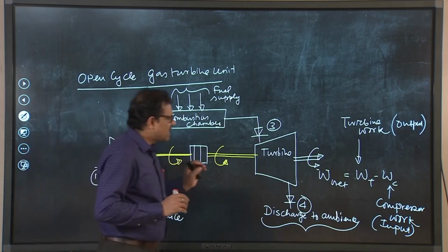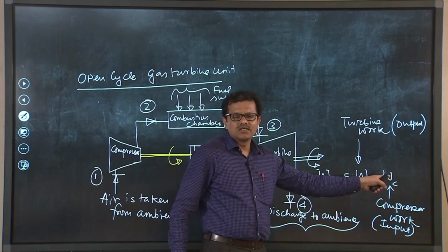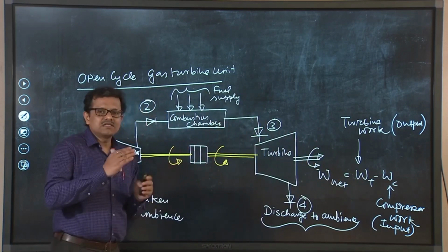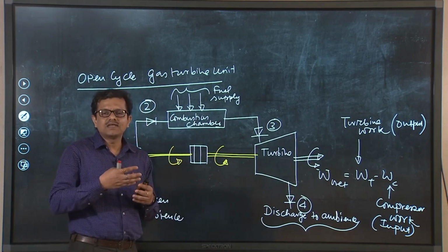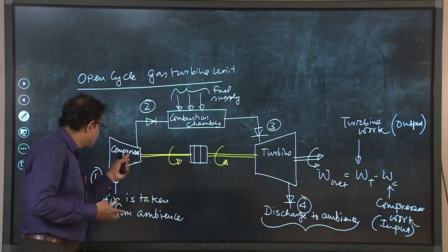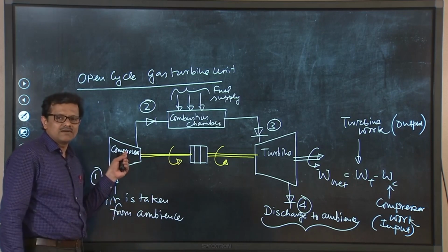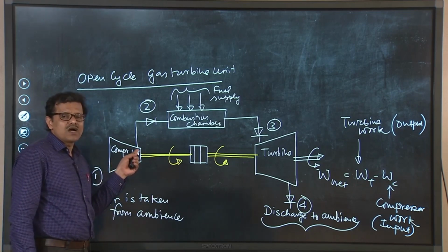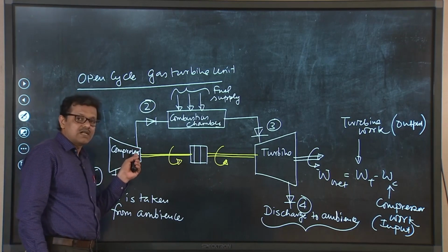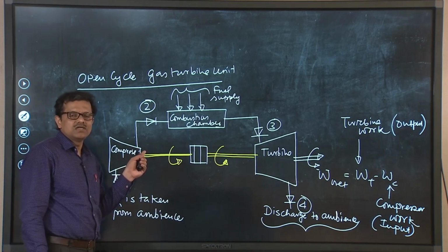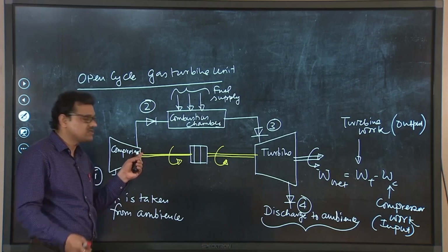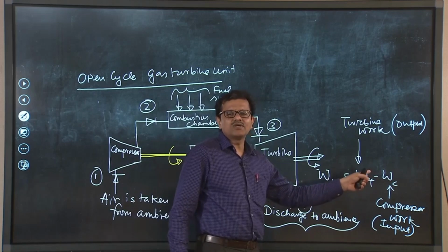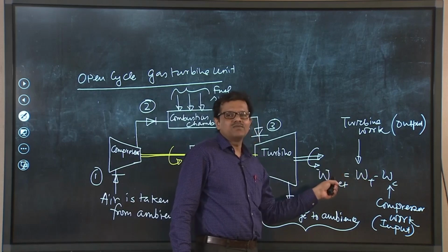Similarly, here I had written that Wc is the work input to this compressor, right. Now, if this is the amount of work needed by assuming the process is reversible adiabatic in the compressor, then the actual work that we need to supply to the compressor, accounting for the irreversible losses, should be more than this. So, essentially what we can understand, the W net will be reduced.